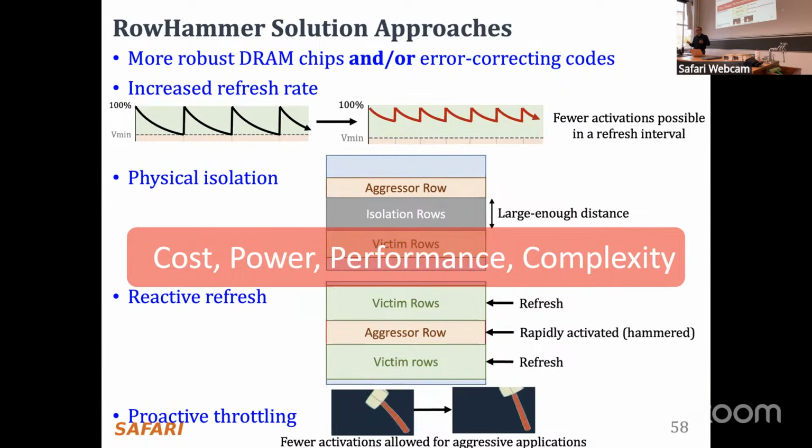I think this is an interesting idea, technically, but if you think about it, what is the benefit of this? I feel, as a principle, the question is, do you really want to move the row somewhere else, or do you want to refresh the adjacent rows? It's good to think about that. If you move the row somewhere else, then you get some benefit. You don't need to know which rows are adjacent to you. That's the good part.